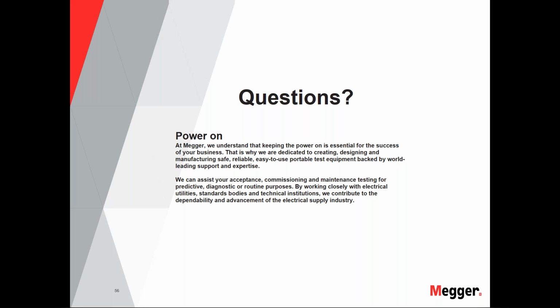Yep. Okay. First thing on the rotor ground fault, we have different methods to protect the rotor, like impedance schemes, like the controlled impedance scheme and the injection principle. In case of the injection principle, it's pretty straightforward. With the generator offline, you can make the ground anywhere, then it will work. For the first and second ground fault in the controlled impedance mode, you can touch the brush to ground at one side in the running condition, not the generating condition, but the running condition, and you can see the ground impedance changes.